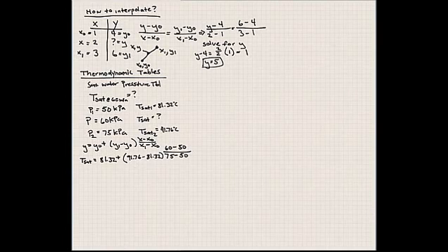So you could run this calculation and you'll see the saturation temperature at this pressure comes out to be 85.5 degrees C. And a rule of thumb, or actually it should always be the case, is that the temperature that we're calculating here had to be between the ranges of 81.32 and 91.76.